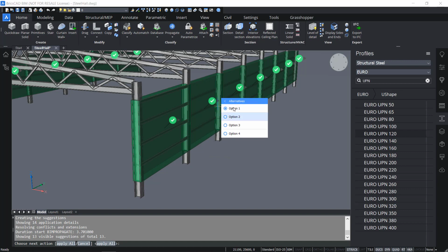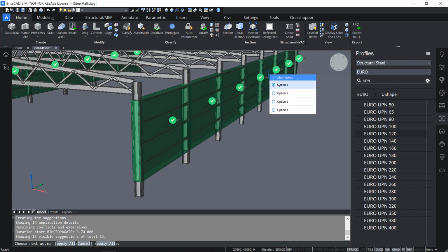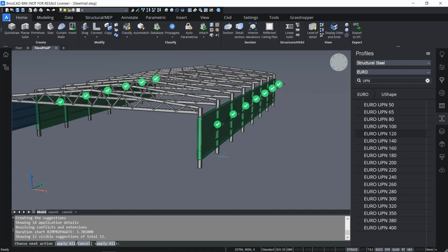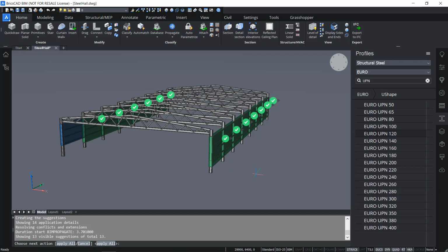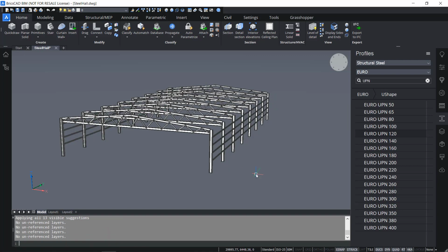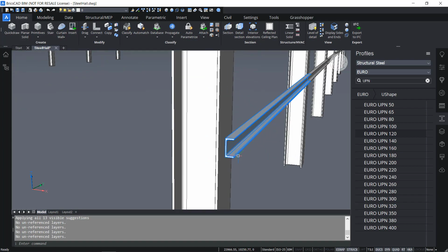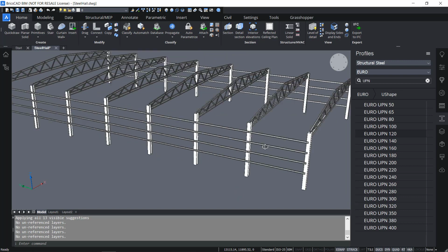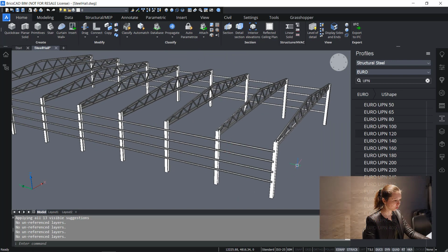And I want to do that for every one of the check marks, so that you always have the sidebars at the outer location of your structure, and then press enter to accept. And then you will see that in fact they are at the outer location. So that's good. We now modeled some sidebars where you could now model further cladding onto etc.